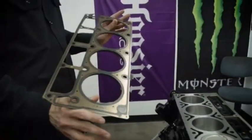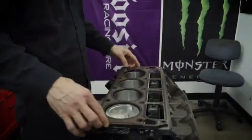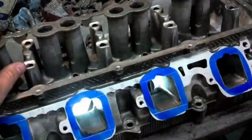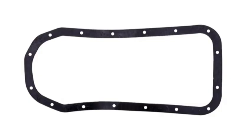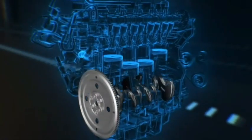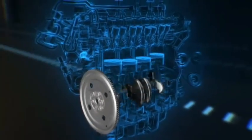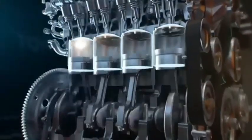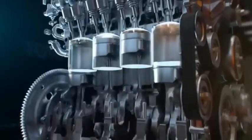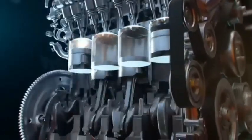In a car engine, gaskets are placed between key components such as the cylinder head and engine block, intake and exhaust manifolds, crankcase and oil pan, and valve cover. Their main job is to seal off internal passages for oil, coolant, and combustion gases, even under high temperature and pressure. Gaskets also help absorb minor surface imperfections between metal parts, ensuring full contact and preventing leaks.